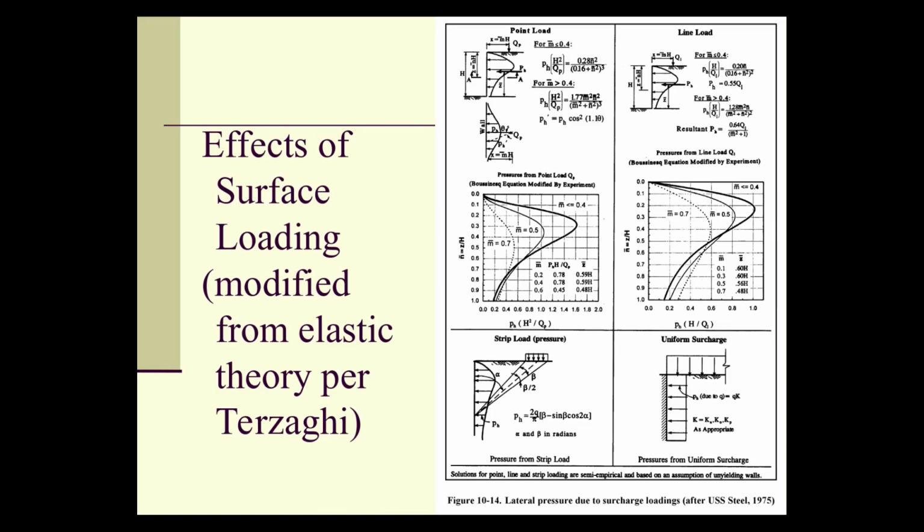equations. Actually, if you look at the line load, for m bar equal to or greater than 0.4, which basically means that the location is greater than 40% of the wall height, the equations are identical. And they show you that. They also, for hand calculations of walls, concentrating the load in the resultant was very common. For computers, they would do a distribution.